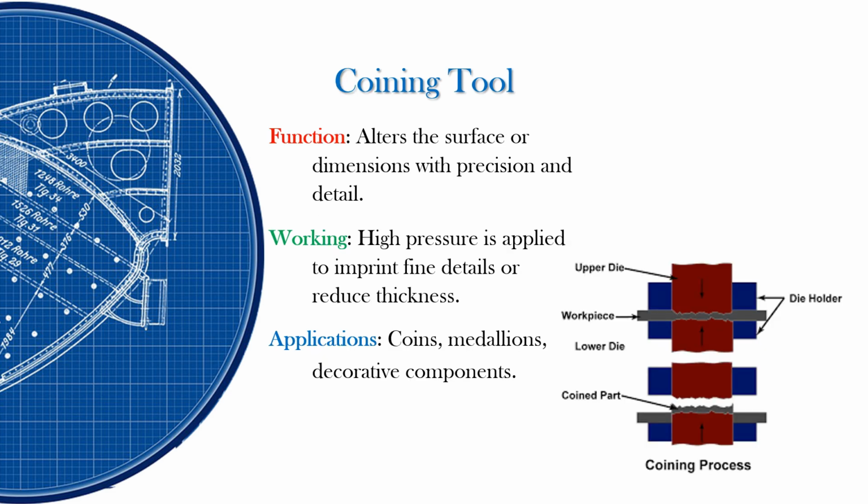Coining tool. Function: alters the surface or dimensions with precision and detail. Working: high pressure is applied to imprint fine details or reduce thickness. Applications: coins, medallions, decorative components.